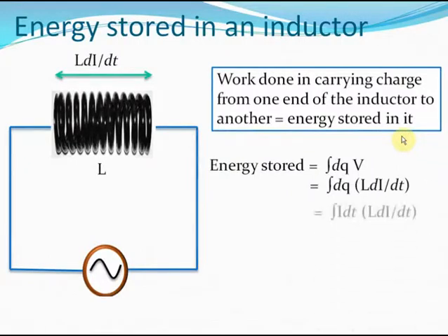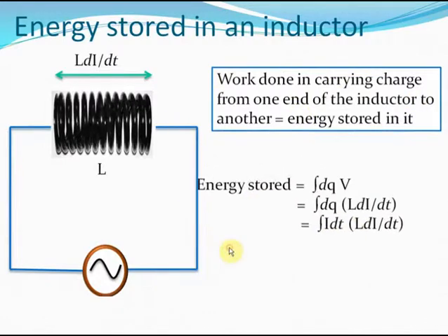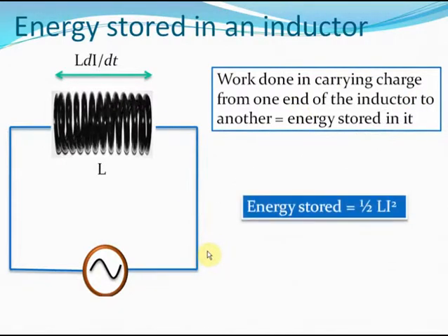So the net energy stored in the inductor will be integral I dt into L dI by dt, or it will be half L i square. So you must remember that the net energy stored in any substance which has a self-inductance L is half L i square. This is very important for competitive exams.